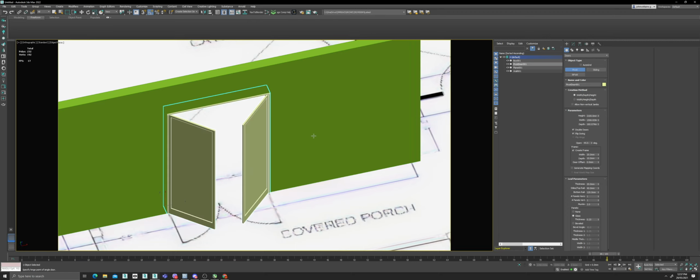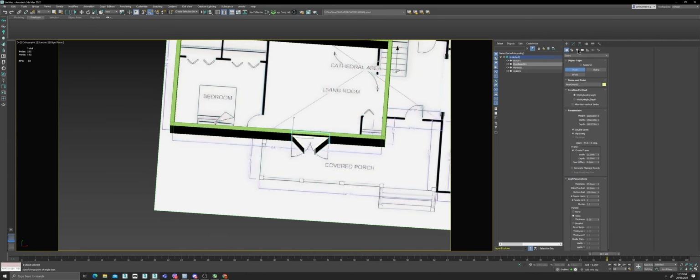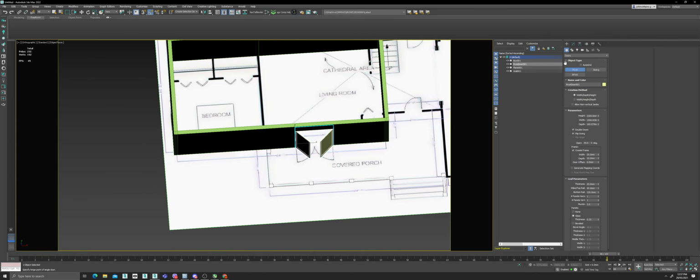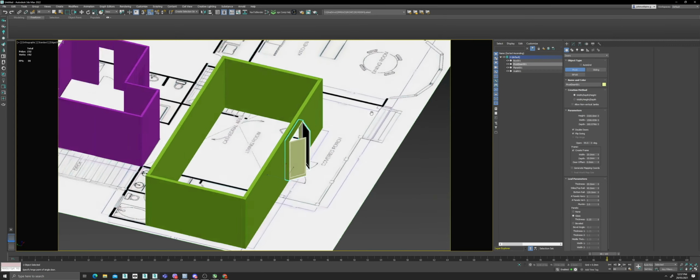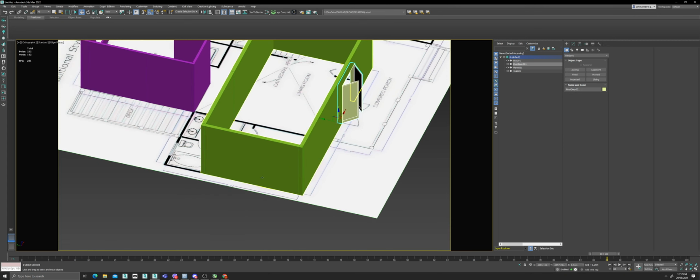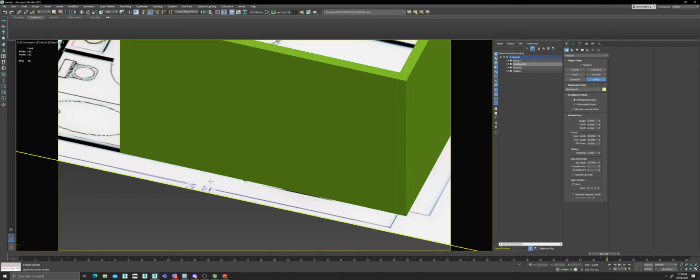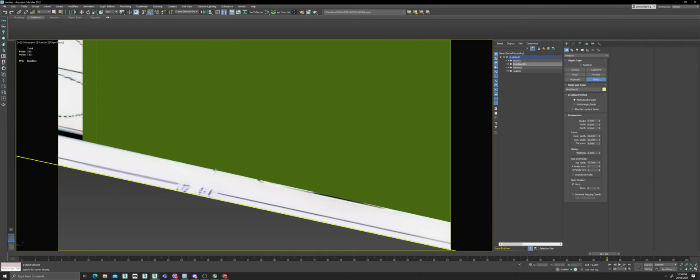That is when you're using AEC walls, AEC doors, and AEC windows. Right? So it's very easy to create walls in 3ds Max. Let's say add a window here. So AEC window. Let's use sliding. So this is the creation method with depth and height. So first the width. Click and hold.